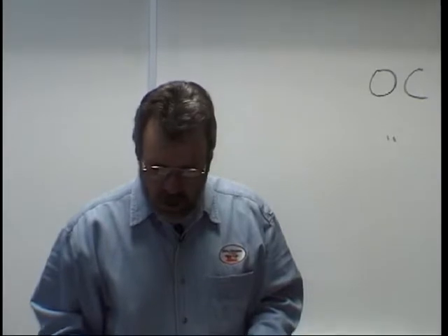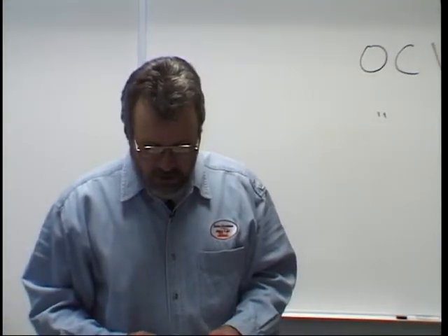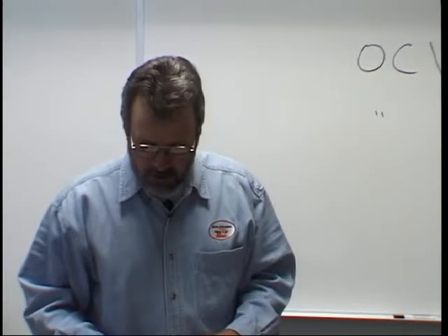Self-regulation of arc length is possible because small changes in voltage cause the machine to produce large changes in welding current. Thus, any change in arc length results in a large change in current and a corresponding almost instantaneous change in the burn-off rate of the electrode. This regulates the current at the arc. Okay? So that's a bullet. Understand the burn-off rate and how that happens. Okay? Next, flip the page.